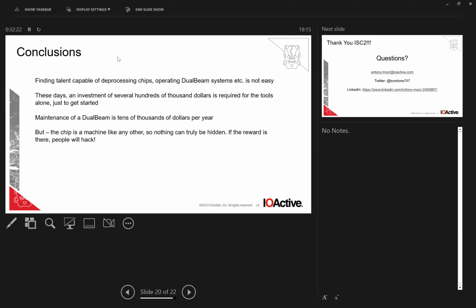This is a significant amount of chemistry in each layer, right? So you mentioned some of the chemicals that are in some of the layers, silicon dioxide and things like that. Yeah, these days it's very, very complex. That cross-section that I showed before was quite old. So you have silicon nitride on the very top, the passivation. Then you have all of the circuitry embedded in silicon dioxide. That's it, pretty much. The metal tracks in that case were aluminium and tungsten. Aluminium for the tracks and tungsten for the interconnects, the vias we call them. And then you have different materials on the surface, at the foot of the sample, the footprint.